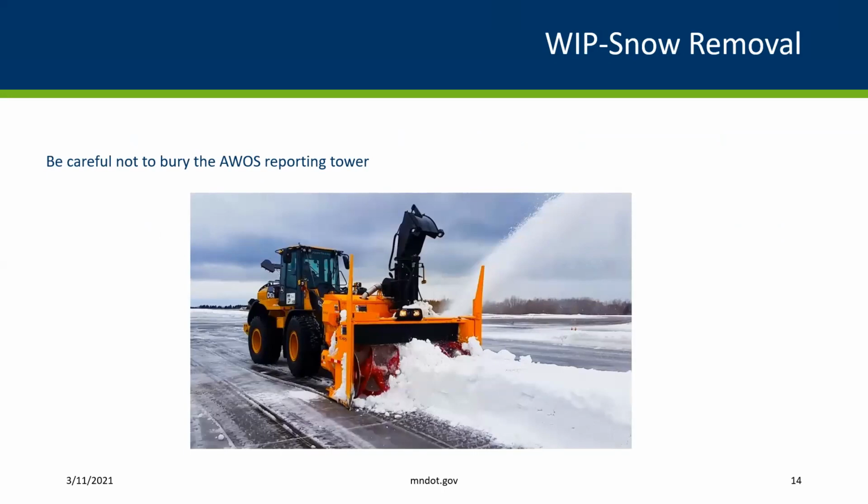When you're throwing the snow, be careful where you're throwing the snow. That can give erroneous readings. It just puts enough moisture and things in the air around the AWAS and or can damage the AWAS machines. Then as we're flying in, your weather system will then report erroneous information about what's actually happening at the airport.